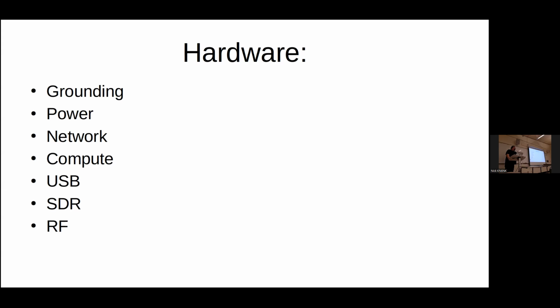What is your website? Post Office Code Standardisation Advisory Group, pagers. One-way pager traffic. When you see somebody in a hospital show and they have a little thing on their waist that starts beeping and they go, "Oh, I'm blah blah blah." That's a pager, and it's probably POCSAG that is being transmitted to for that to pick up. Either that or FLEX are the two major protocols.